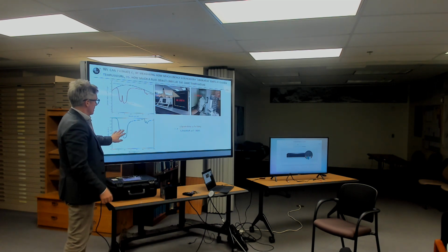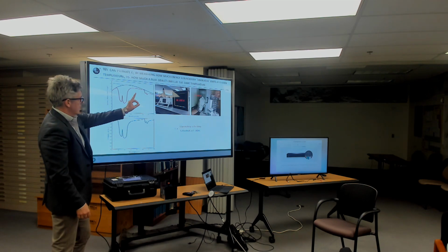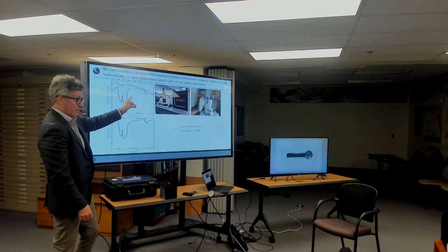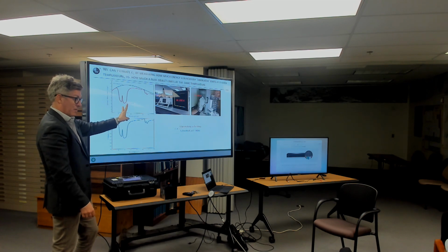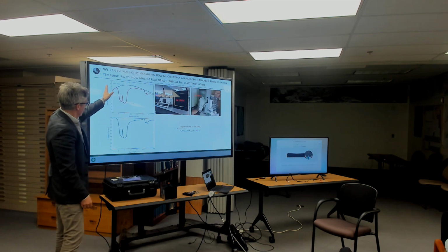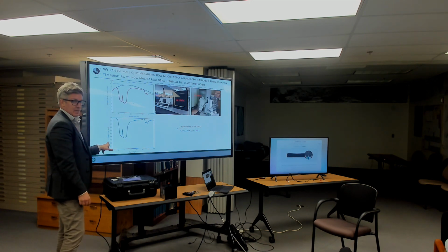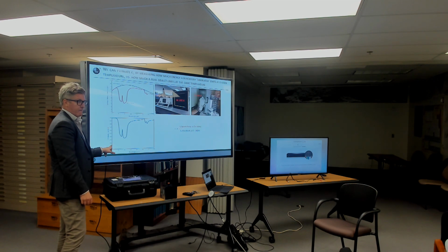To work out the emissivity, we would measure the emission from our real object at a temperature and then normalize that to the black body flux at the same temperature and just divide one by the other, and that's how we compute the emissivity. Okay. Anything mysterious about that? People happy?